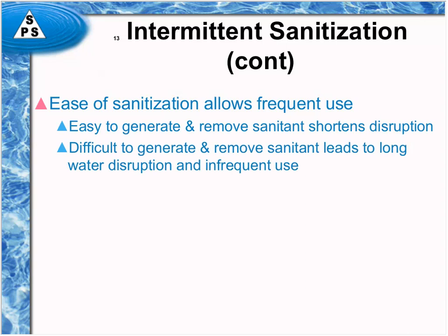If it's difficult to generate and difficult to remove the sanitant, it tends to lead to much longer water disruption. And when you have water disrupted for a period of time, production is shut down. And they are not in a mood to be shut down too frequently. And so that leads to infrequent use of these sanitization approaches, which is really unfortunate because it needs to be used frequently in order to stay ahead of biofilm. So if you don't use it frequently, then you are not staying ahead of biofilm and you'll have problems killing it.